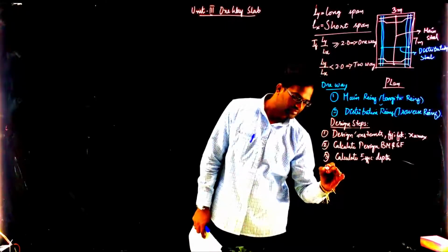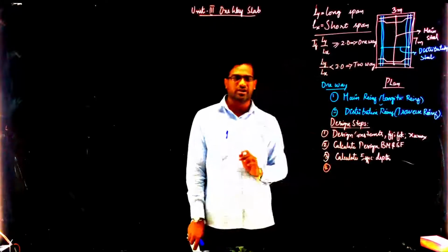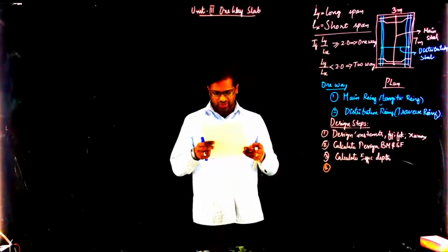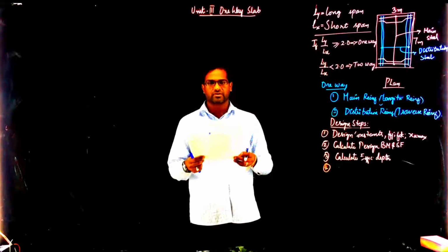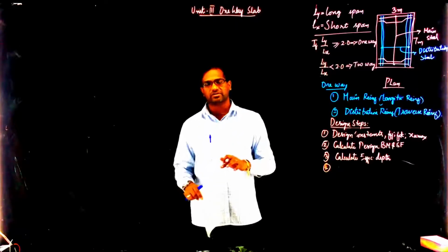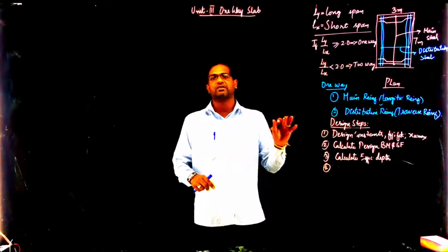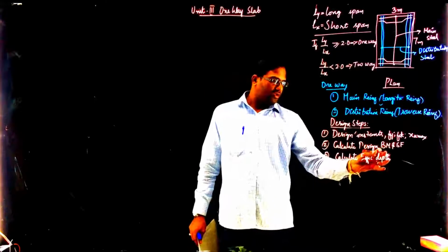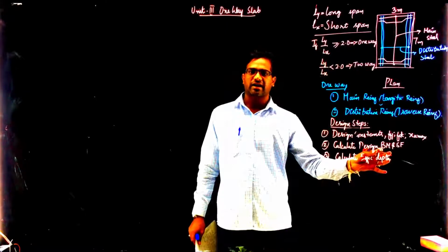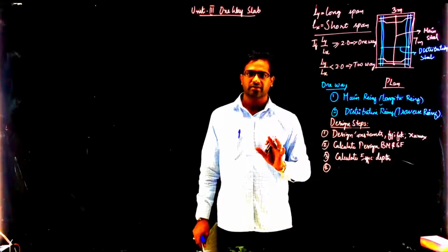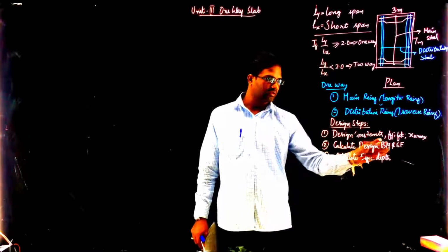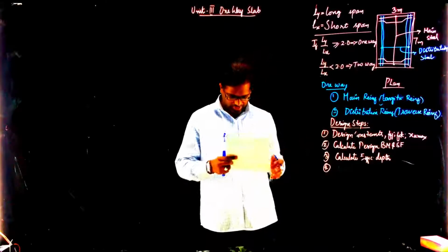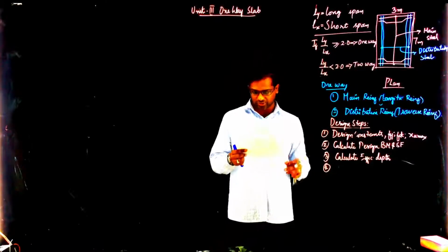Now, the fourth step is to check. When you know the effective depth and the design bending moment, you need to check whether the provided depth is good enough to take the required depth. In the effective depth calculation, we will calculate the required depth, right? And for the given bending moment, we will sort it out. We will know when we are doing the problem.